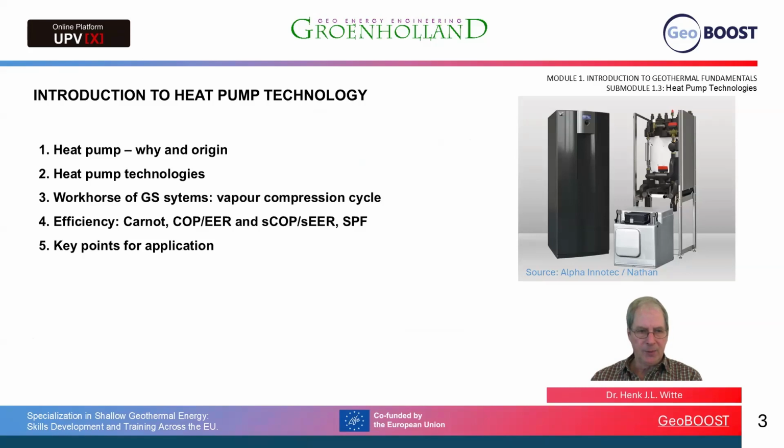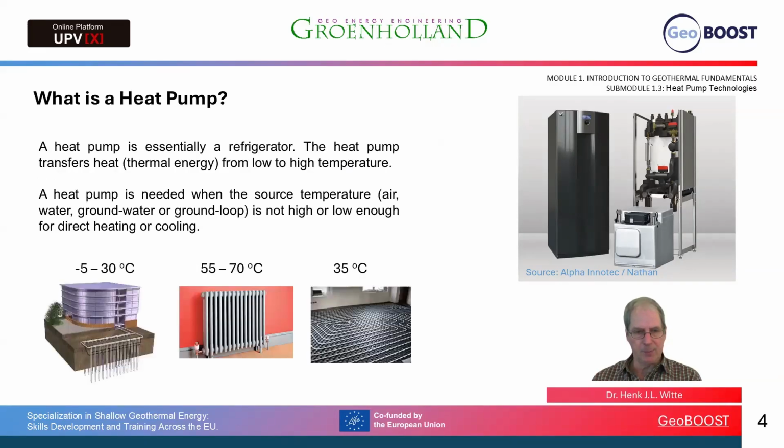And then we'll take a little bit more detailed look at the workhorse of ground source energy systems, the vapor compression cycle, after which we'll discuss efficiency, theoretical efficiency, Carnot, and then more practical coefficient of performance and energy efficiency ratio. We'll round off with some key points for the application of heat pumps.